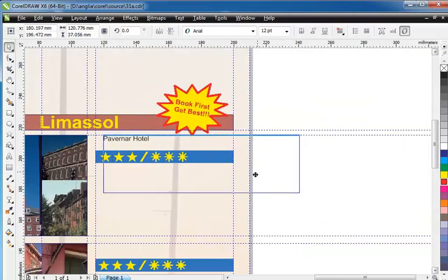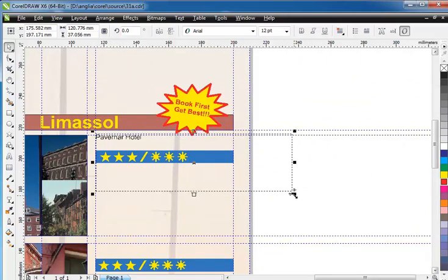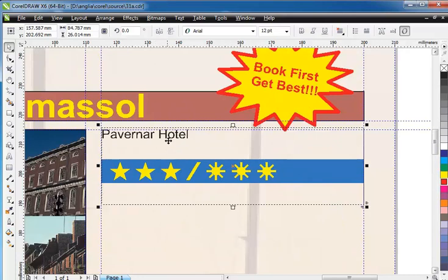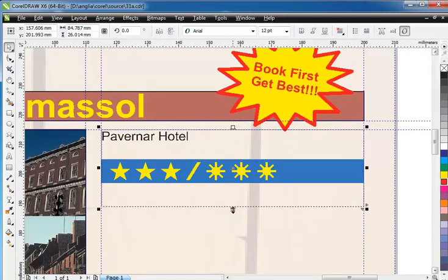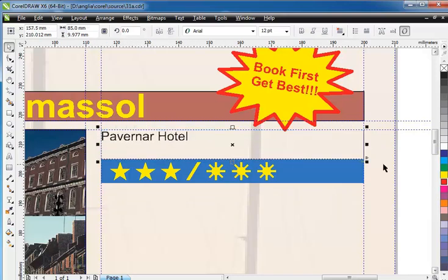Move the text box over the first section. Now downscale the box and make it fit in the section. Make it fit in the space between the guideline and the blue rectangle. Use the transformation points to change the size of the text box if you need to. Of course, we can just change the height of this text box into a specific number. Change it to 10mm and press Enter.